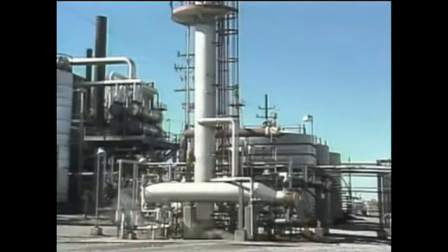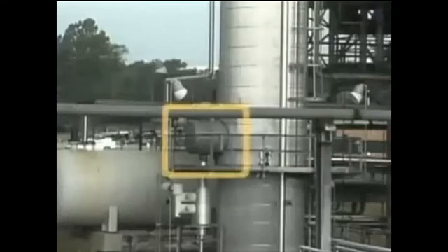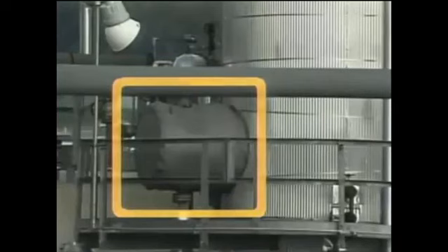Another way that reboilers can be identified is by their location in relation to a distillation tower. A reboiler that is located outside of a tower is an external reboiler. All of the reboilers we've seen up to this point are external reboilers. A reboiler that is mounted directly into the bottom of a distillation tower is an internal reboiler. This particular internal reboiler is often called a heating element or stab-in reboiler. In general, internal and external reboilers work in much the same way. Steam or another hot fluid is used as the heating medium, and the vapors or vapor-liquid mixture that is produced is used in the tower to provide heat for distillation.